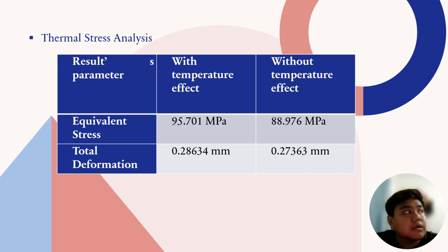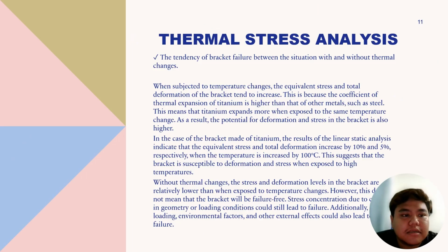Firstly, we got the equivalent stress of 95.701 megapascal, and without temperature effect we got 88.976 megapascal. For the total deformation we got 0.28634 millimeter, and without the temperature effect we got 0.27363 millimeter.